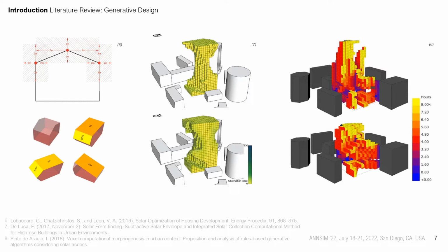In performance-based design, environmental factors like solar radiation and daylighting are improved by simulating a building form's massing, orientation, shading devices, and so on. The iterative nature of generative design makes it an ideal early-stage design approach by allowing for rapid exploration of countless design alternatives. This provides an opportunity to find higher performing solutions when optimizing for sustainability-related objectives is demanded, for example, increasing solar energy potential.